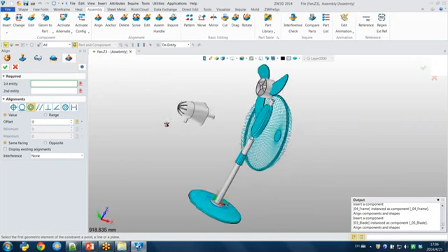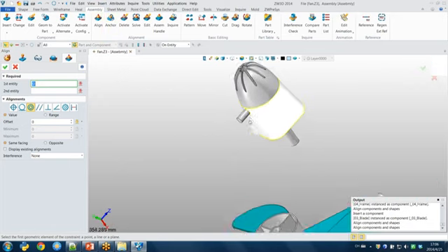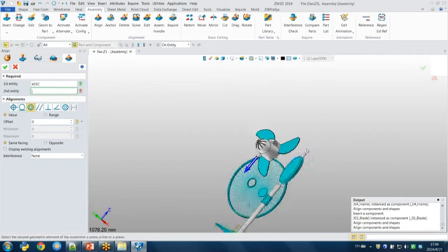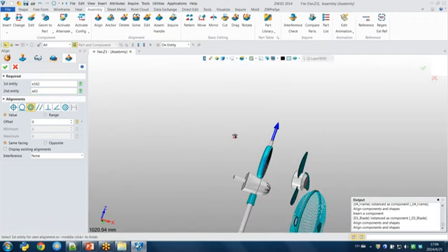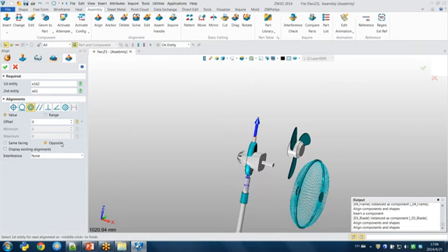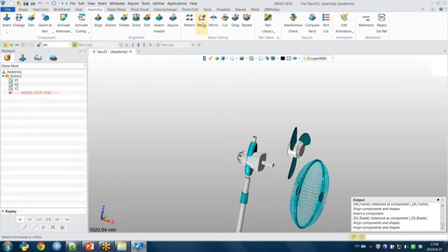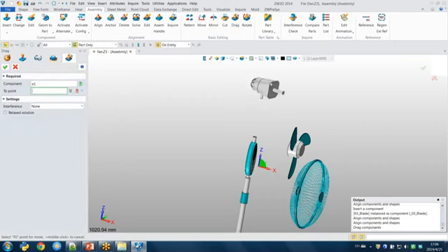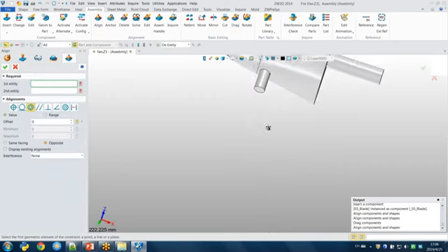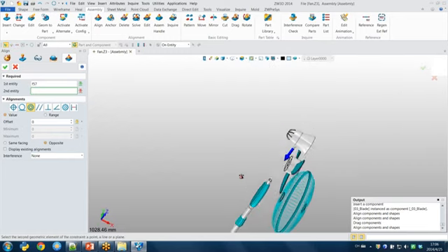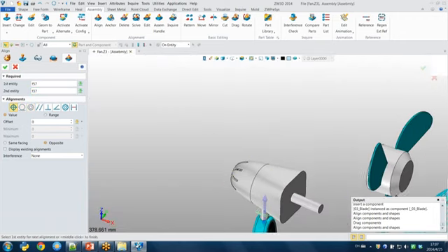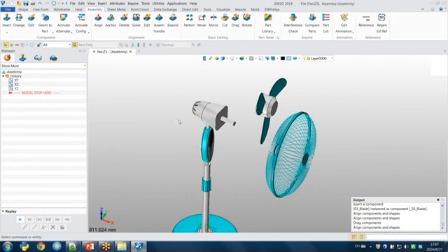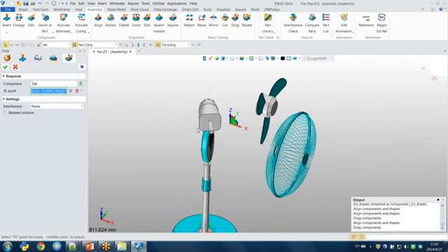Okay. So same, align the power first. That's okay. Move. Next, align the surface. This surface and the surface inside, and press OK. So after you make the alignment, you can find this one can drag totally at 360 degrees.